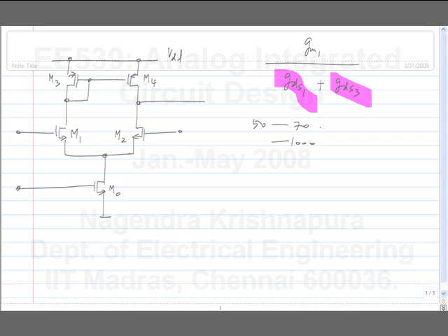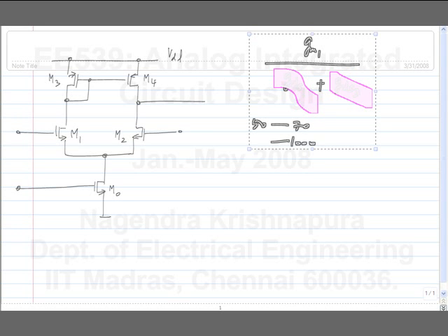You have a feeling that this is not going to cut it, right? Because you have to increase the length by 50 times. That's not happening. First of all, even if you are able to do it, the parasitics will increase so much that your phase margin will deteriorate drastically. So what else can you do? So this is the point at which we need a change in architecture, not just playing around with parameters of the given circuit. What can we do?